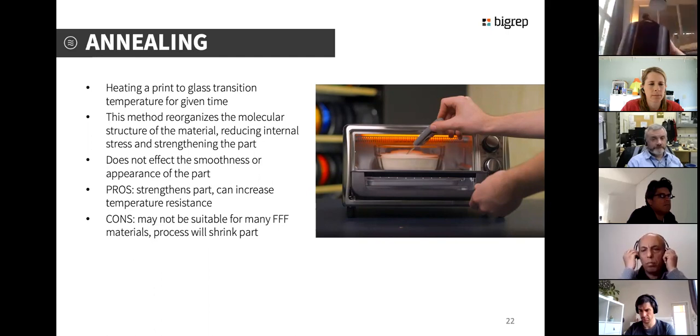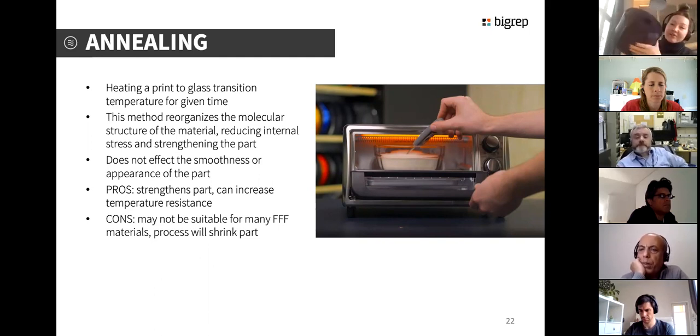I don't think this is the actual one, this is just a sample of the one we did, because we used a different material that was specifically made for high temp and for annealing. Basically we printed this, and we put it in the oven by itself beforehand to anneal it, which then made it more temperature resistant for the later mold making process.